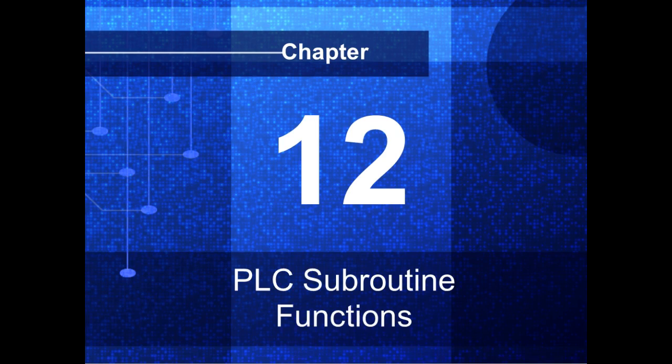And if I had to go into every PLC that I've got and reprogram that e-stop circuit in there, that's going to take a long time, right? But if I save it as a subroutine, and then import it into my next application, then you save all that programming.